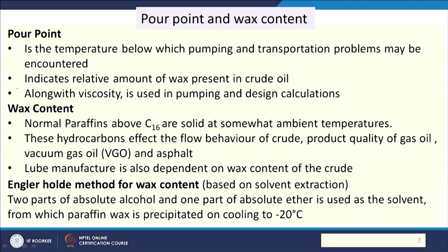Another property is pour point and wax content. Pour point indicates the flowability, that means it is the temperature at which the fuel ceases its flow. It is related with the wax content also, the more wax, the more easily it ceases to flow. Along with the viscosity, this is also used for pumping design.